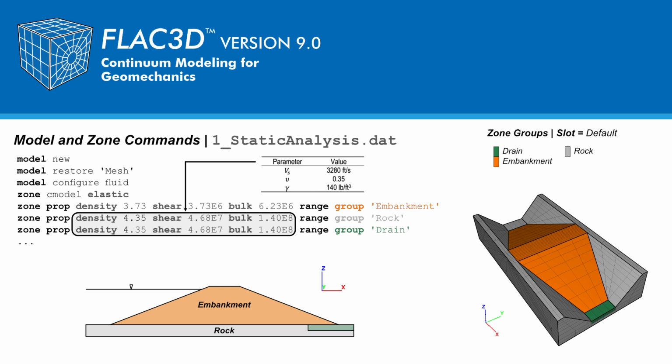In this analysis, the actual blanket drain is not explicitly modeled, but instead a row of numerical zones beneath the downstream toe of the embankment. In addition, because of the need for a simple numerical mesh with less than 1,000 numerical zones, the zones for which the drain material is assigned are in a region that would have normally been rock.